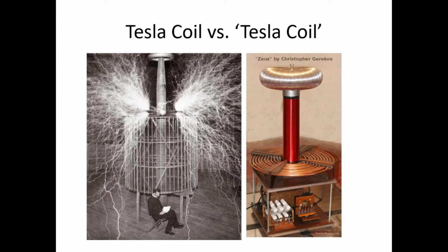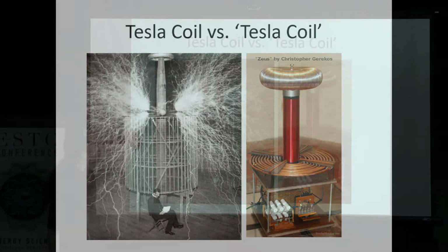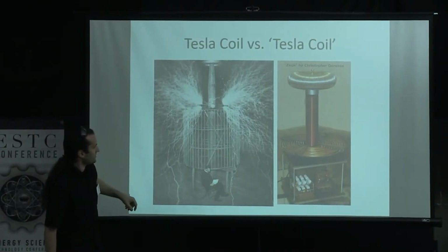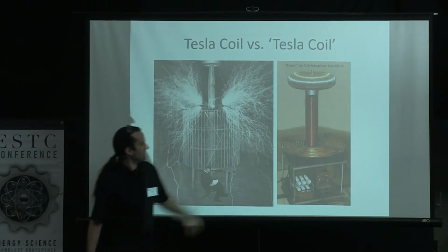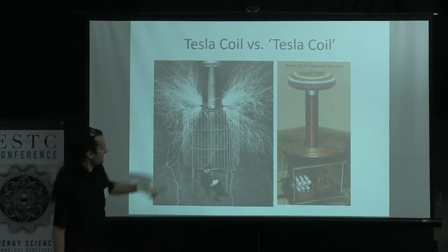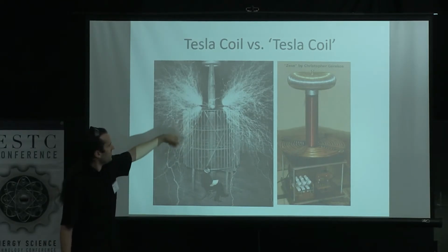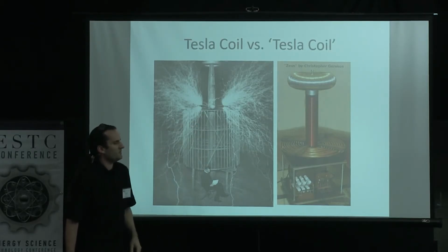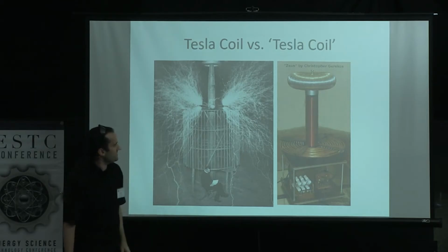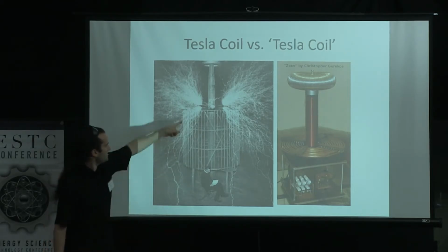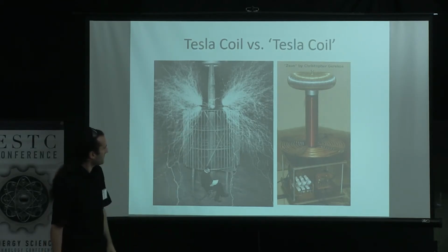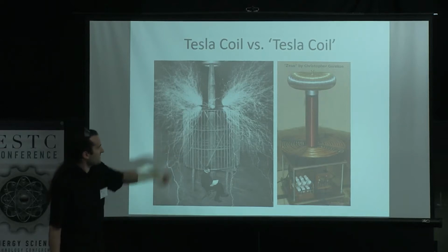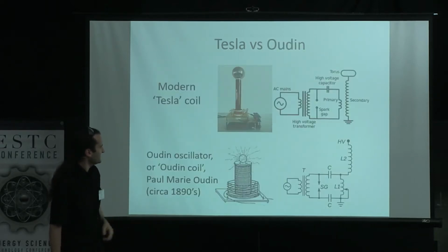So we'll notice the extra coil on here is missing. That one only has 2 coils. The primary on here was 2 turns of thick strap. Primary on there is closer to 10 turns. The secondary on here, which we'll call the high voltage coil for purposes, is many hundreds of turns of copper wire, whereas this one is less than a couple hundred. And you'll notice that one's not sparking very good, and that one is.